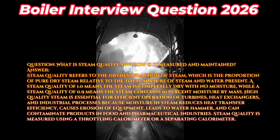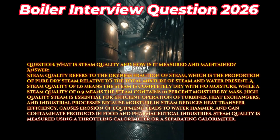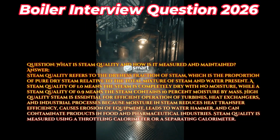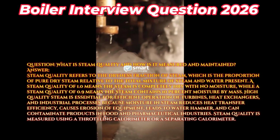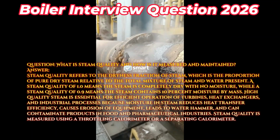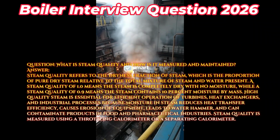Question: What is steam quality and how is it measured and maintained? Answer: Steam quality refers to the dryness fraction of steam, which is the proportion of pure dry steam relative to the total mixture of steam and water present. A steam quality of 1.0 means the steam is completely dry with no moisture, while a steam quality of 0.9 means the steam contains 10% moisture by mass.